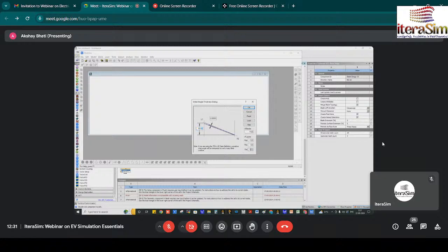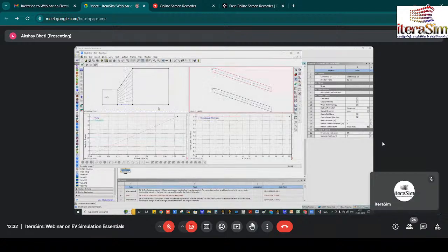And here I told you about the cascade system that divides the leading edge to trailing edge into 10 small layers. Mostly I consider 10 mm layers, and mostly we will develop 8 blades for the fan. You can also increase the number of blades depending on the requirement. So that is the leading edge, that is the trailing edge, that is the angle, and that is the thickness. You can also change the thickness of the fan from leading edge to trailing edge according to your requirement.